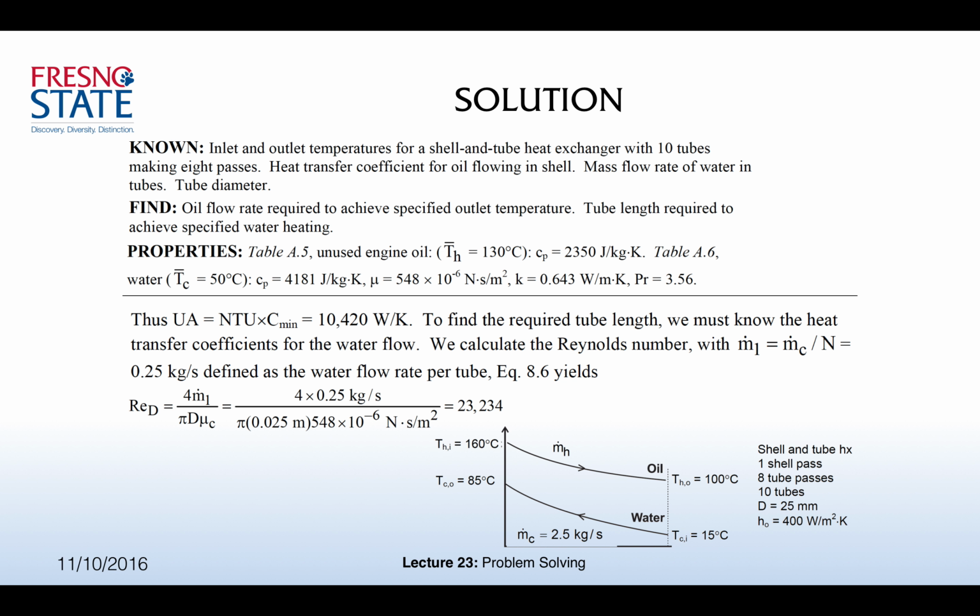I remember that would be 2 weeks ago. And therefore, as usual, I need to find the Nusselt number and therefore the h. In order to find the Nusselt number, I need to start with the Reynolds number, find whether the flow is laminar or turbulent, and therefore pick the right correlation for Nusselt number.